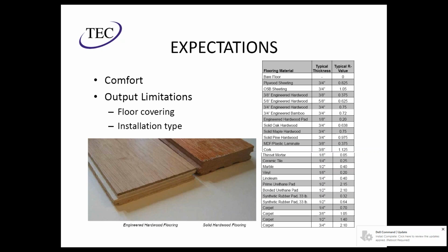So in terms of expectations, obviously radiant is prized for its comfort applications. It creates a great temperature gradient from floor to ceiling, so everyone is more comfortable. But at the same time, there are limited outputs for it. It does feel slightly different than a traditional heating and cooling air system. So it's all things that you need to cover with the customer when they initially come to you for this option.